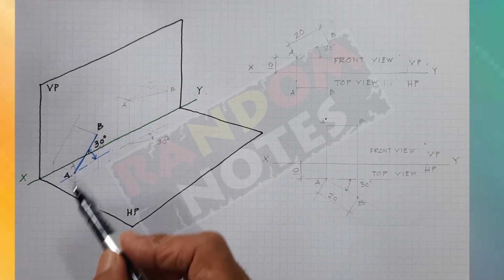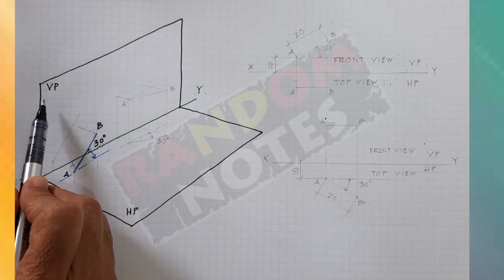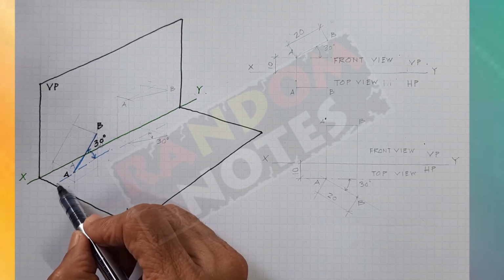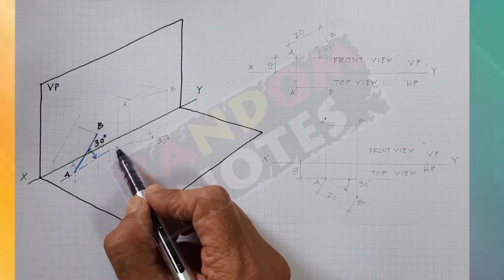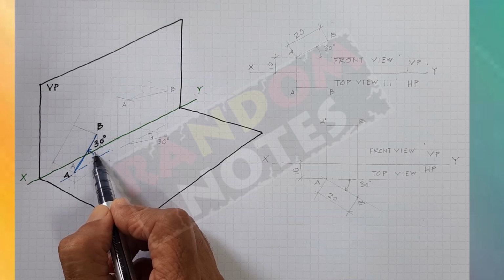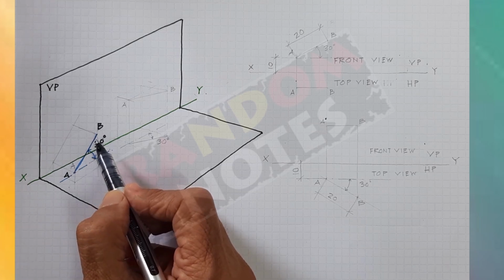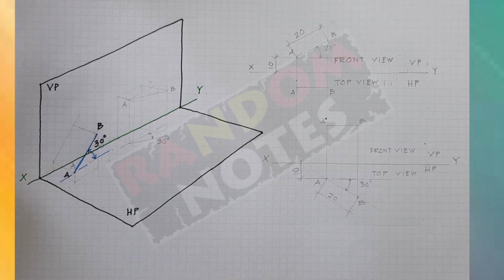In this first condition, we have line AB which is parallel to the vertical plane, but it is inclined at an angle of 30 degrees from the horizontal plane. So this dash dot line is the horizontal line which is parallel to the horizontal plane. From there it is at a 30 degree angle where we have placed line AB. We will try and understand how this will get projected on the vertical plane and the horizontal plane.